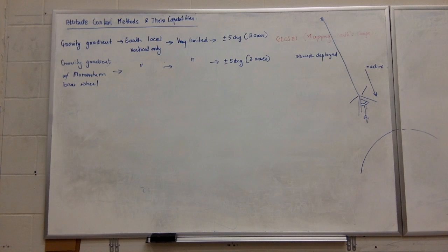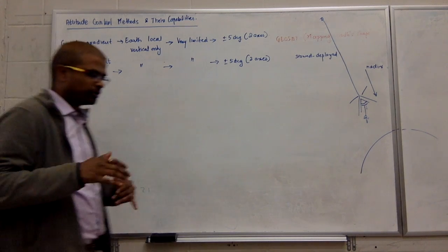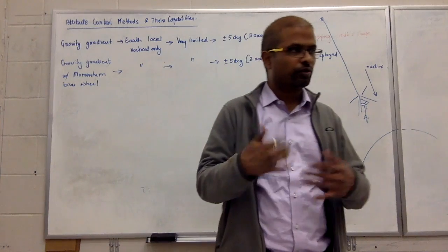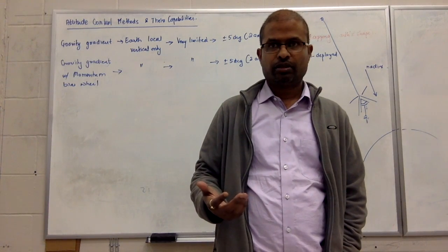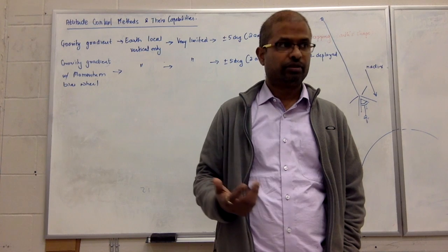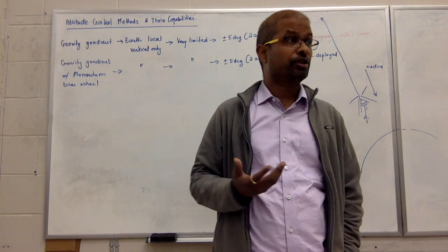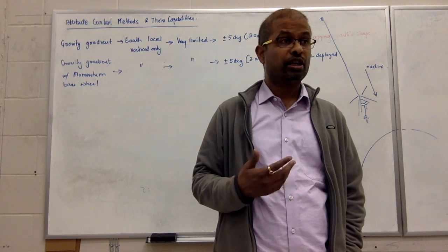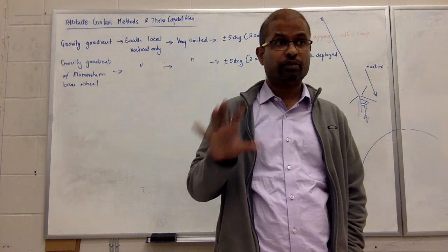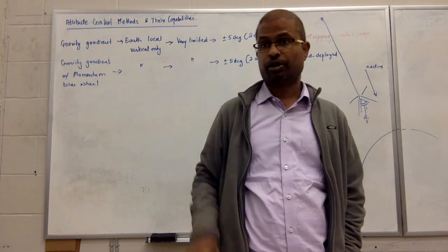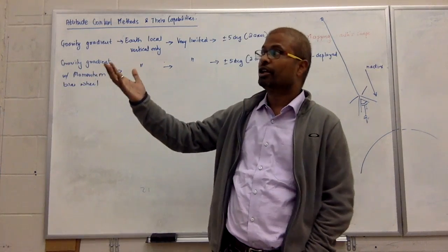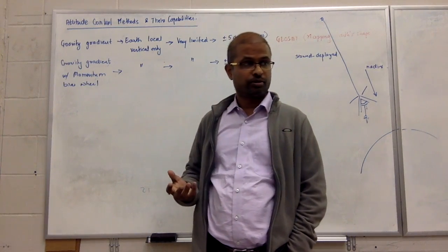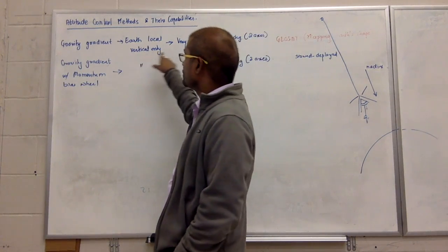Now, it is not like what you see on the ground. When something gets launched from ground to space, what changes? The temperature changes significantly, there is cold welding, and the pressure changes significantly. So you cannot do a design which works on the ground and expect it to work in space. You have to be very adept with that, and you can get really creative with mechanisms.